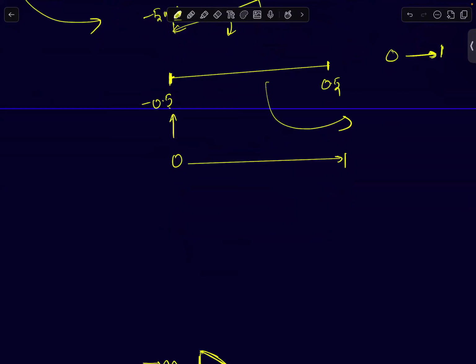The first step I need to do is an amplification by a factor of 100. So if I have VI, I need to do 100 VI. So that's my first step. And then I need to add an offset, VCM or V offset, some common mode, some DC. Let's call this VDC. This has to be equal to 0.5. It can be any programmable value, but it has to be 0.5.